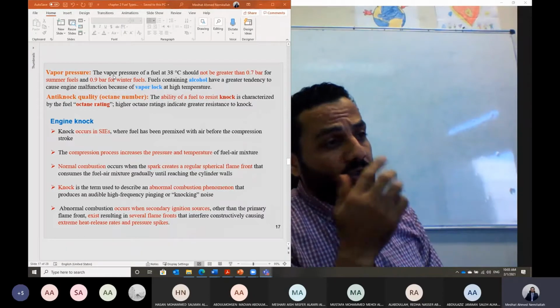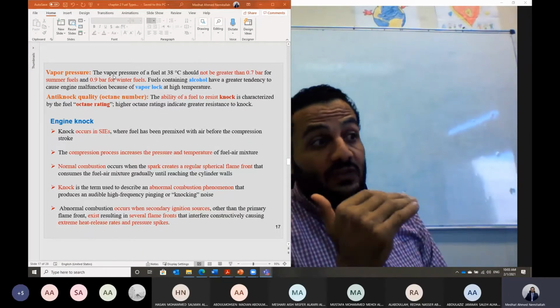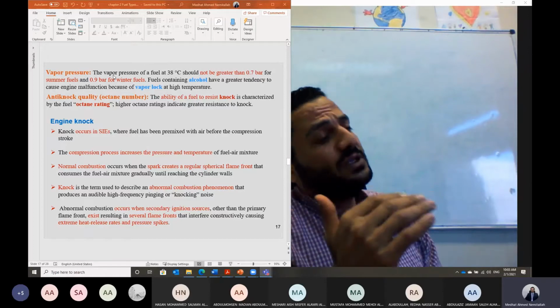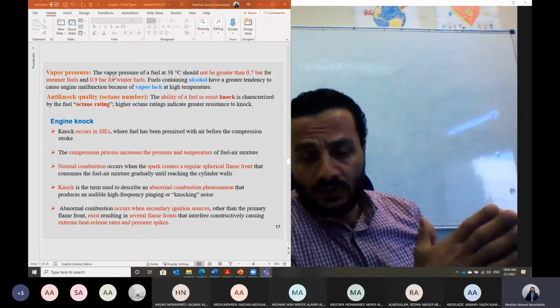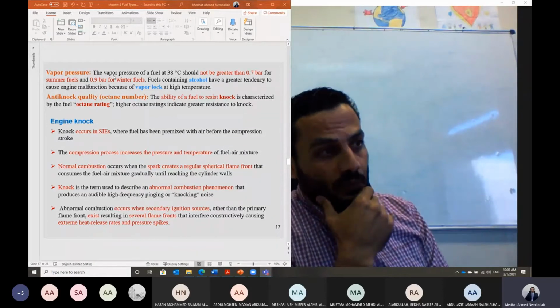But this vapor pressure, guys, should not be below a certain value, because if the vapor pressure is very low, that means more fuel will be evaporated at the engine cold start, and it will cause what we call the vapor lock.